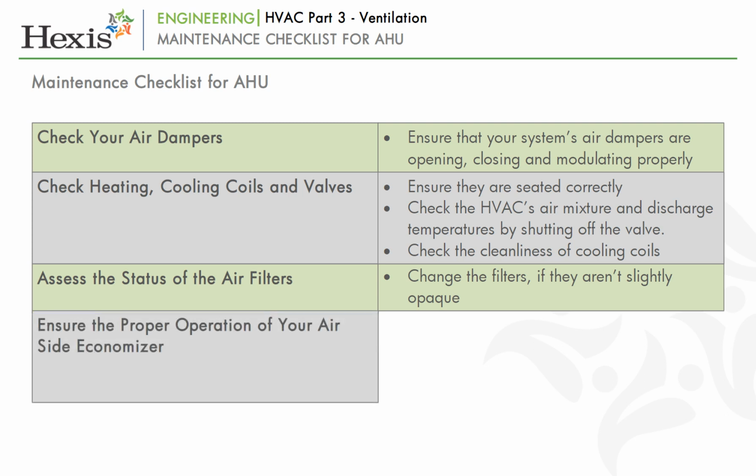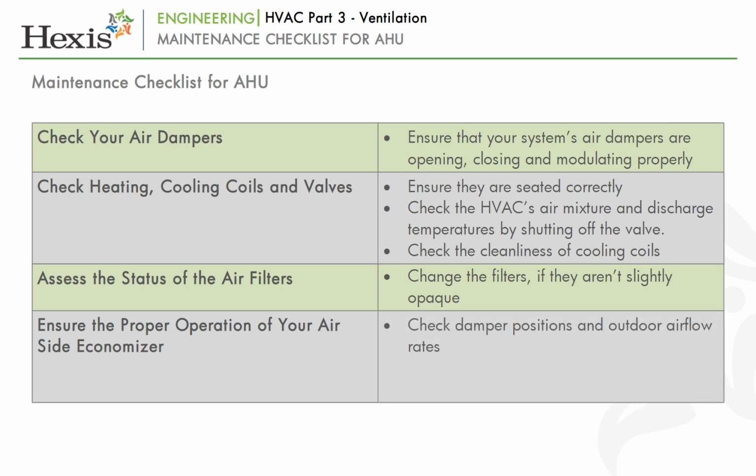Ensure the proper operation of your air side economizer. Some HVAC systems have air side economizers that have outside air temperature sensors and outdoor relative humidity sensors that need to be operating properly. Your economizer functionality can be assessed by viewing damper positions and outdoor airflow rates.